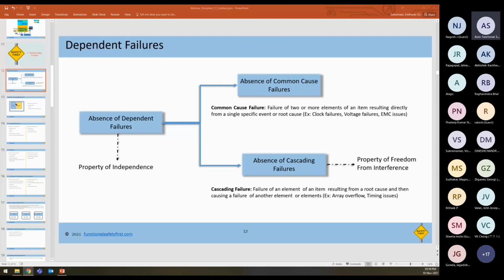But let's say your watchdog may not be petted because of a stuck-at issue in software, which can be a stuck-at issue in QM software or ASIL software, or it can be any fault. Because the watchdog is not being petted at the required timeout, you cannot say that a safety software is stuck or a QM software is stuck. You cannot nail it down until you analyze.